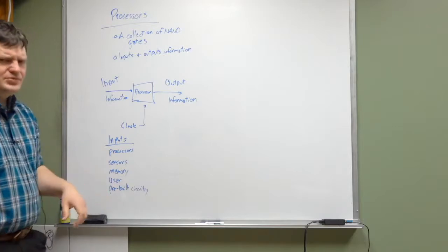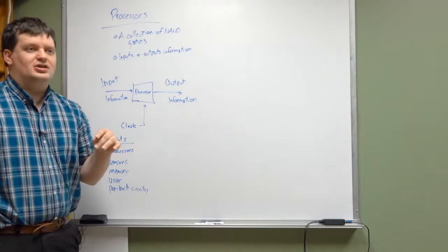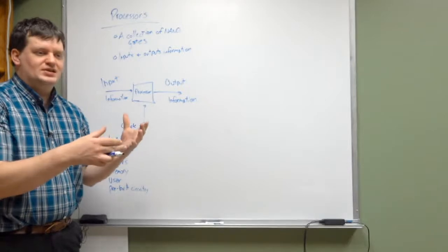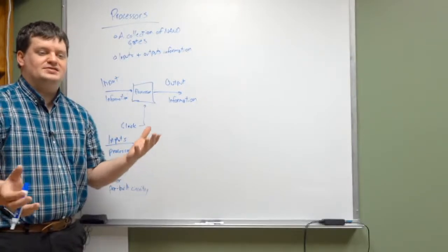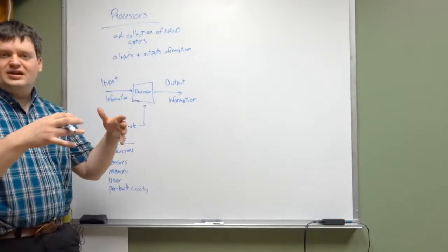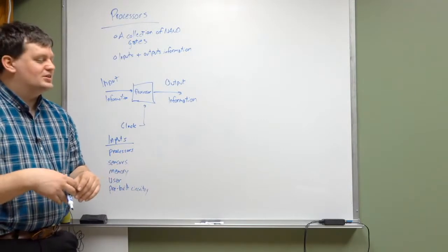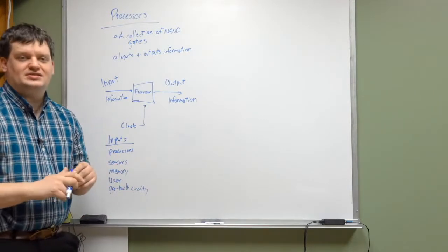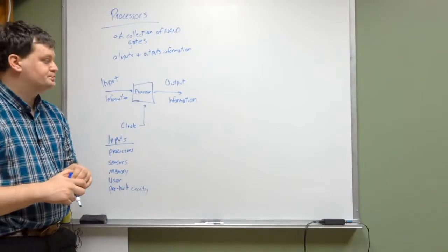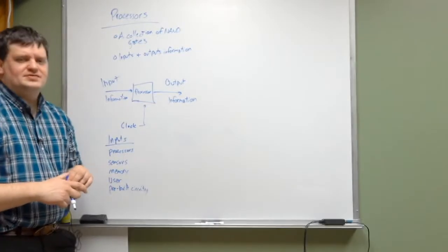So you will have some pre-built circuitry in there. It's why a lot of processors are either wired directly to a chip. What they'll do is put it on there, and it's a solder compound on this printed circuit board, and you put it in an oven and the solder compound melts and sticks the component to it. Allows for a really nice connection. That's how a lot of circuit boards are made. That's one way to do it, but it's a really intensive process.